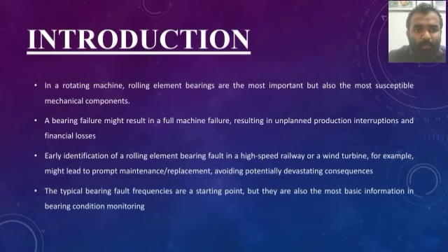When a bearing is operated at a given machine rotation speed under given loading circumstances, defects or faults existing in the bearing create the distinctive defect frequency component in a signal. Alternatively, throughout a bearing's operating life, fault signals might be created as a result of the natural wear process.